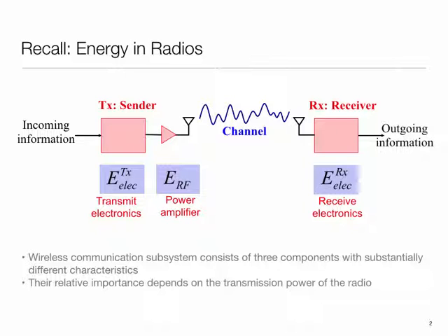And in that case, what kind of power management is most effective? You basically have two strategies, right? Shut things down, or scale things so that they just take the right amount of time. So not turning off. When the transmit power is high, your strategy is to slow things down, because when you slow things down, to send the same bit you need less energy. It's the counterpart on the processor side.